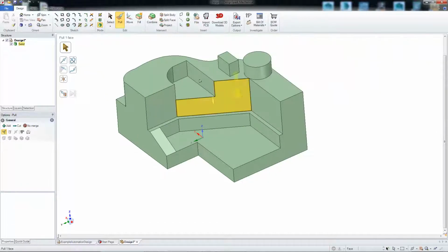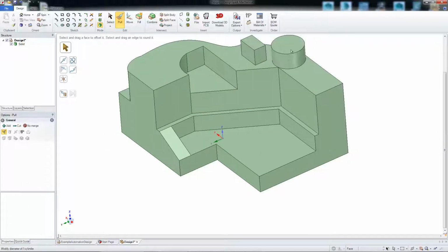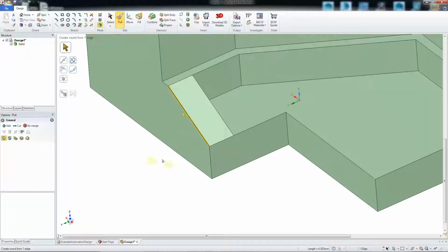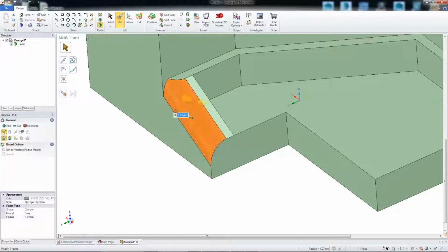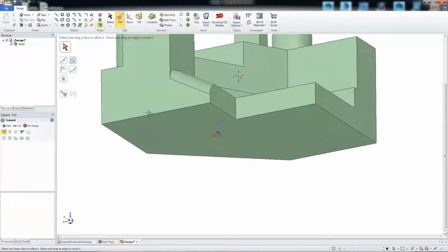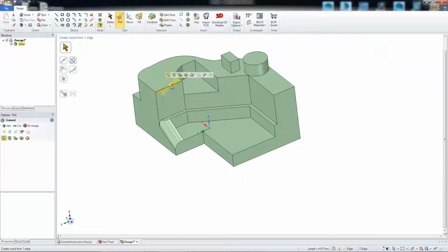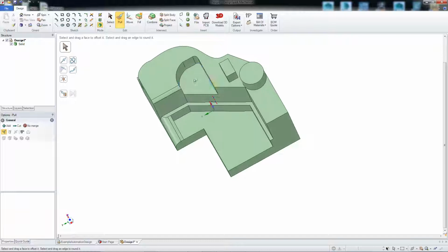Right now, everything looks pretty blocky, but you can definitely go in and start adding some nice detail, like here. Just click on this edge here. I'm going to use the pull tool, which will create a fillet and just rounds out the edge. I use that feature quite a lot. And you can go in and start to get some clean edges here.